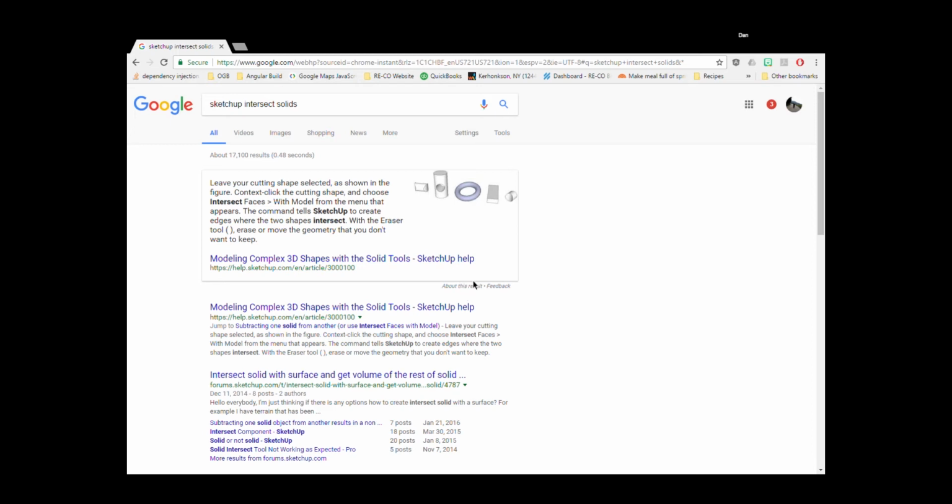Okay, so when I went to move this line, what I needed to do was snap this to the blue axis to make sure that I wasn't changing any other size, wasn't skewing the 2x4. Snap to blue. There we go.